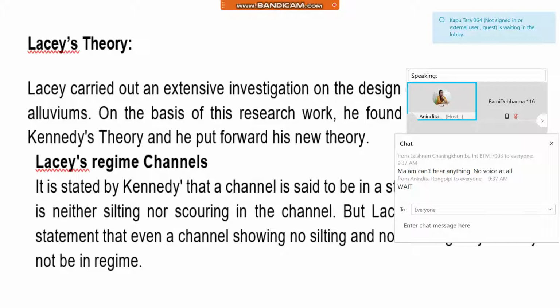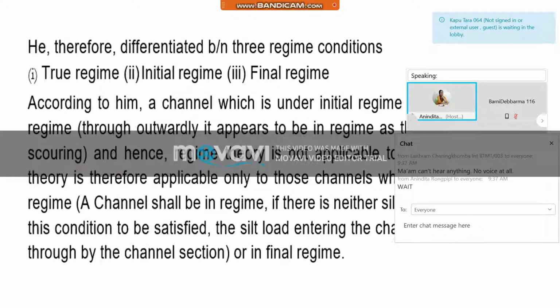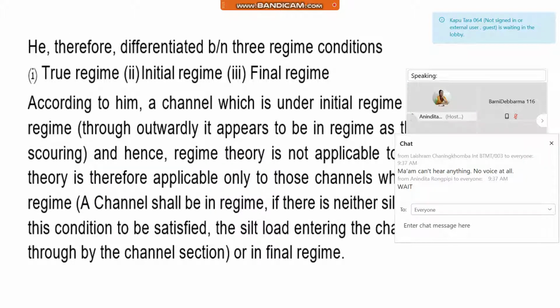It is stated by Kennedy that a channel is said to be in a state of regime if there is neither silting nor scouring in the channel. But Lacey came out with a statement that even a channel showing no silting and no scouring may actually not be in regime. So he therefore differentiated between three regime conditions: true regime, initial regime, and final regime.